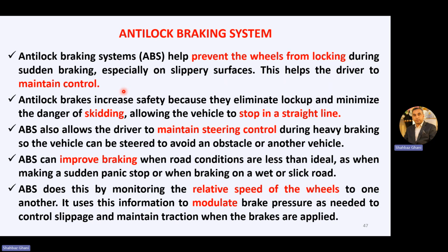But if the vehicle is equipped with ABS system or anti-lock braking system, the skid portion is minimized. We apply a brake, the brake mechanism comes into action and it stops the wheel and there is pulsation. So the wheel is not locked.